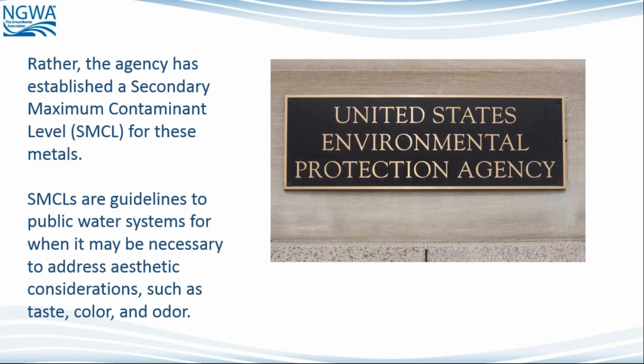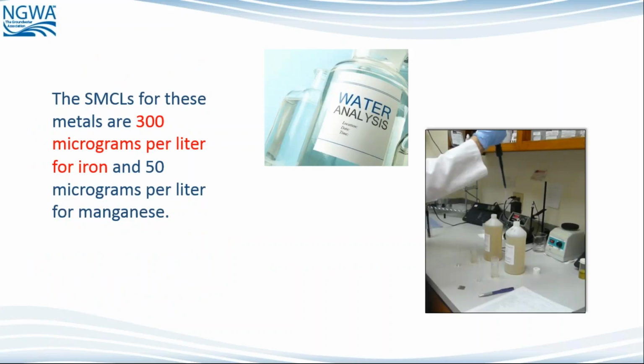And right now, the EPA has placed the iron and manganese maximum contaminant levels for municipal water into the secondary category, which are really recommendations as to levels that may present some aesthetic considerations if you exceed those levels. So they're not in the primary regulations, which require you to do certain things if you have excessive concentrations, but they're in a recommended area where we might have need to watch them and avoid the aesthetic issues, predominantly taste, odor, and color that we talked about earlier.